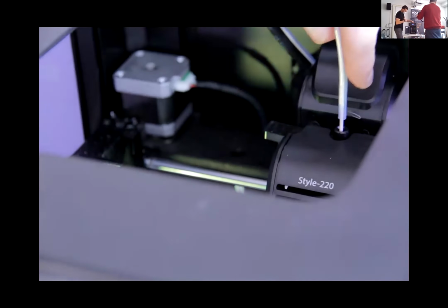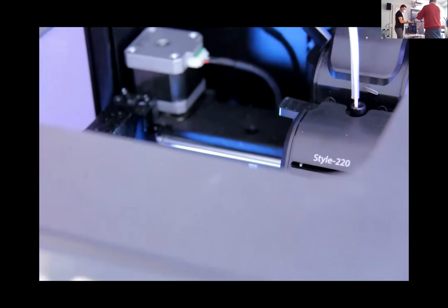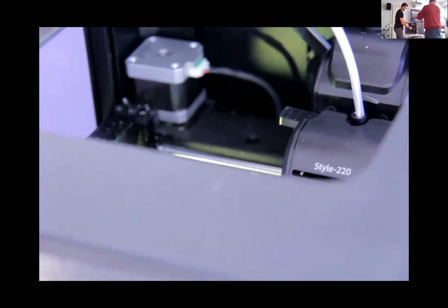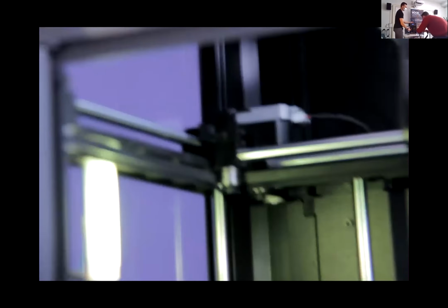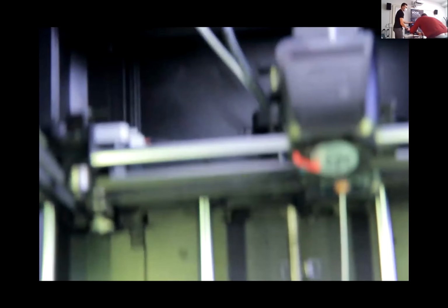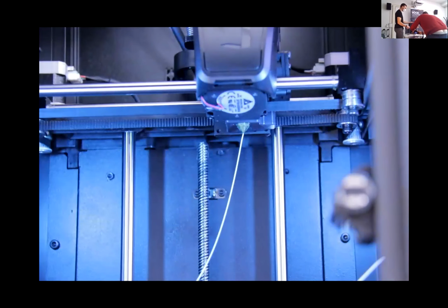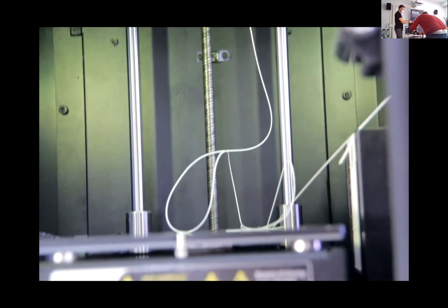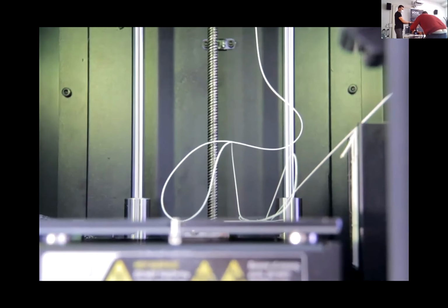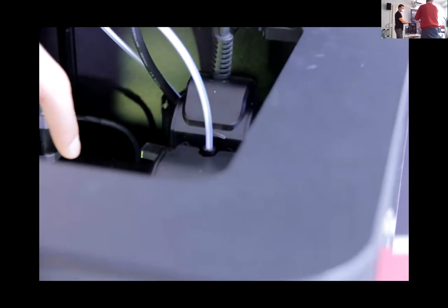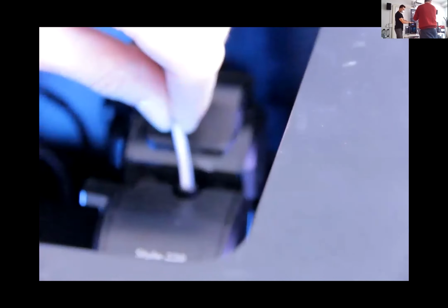There we go. So it's actually pulling on the filament now, pulling it through the printer. And if you look down at our nozzle, you can see the filament coming out that it's pulling in to the hot end, which is great. Let that go a bit. And we also want to make sure our Bowden tube is pressed into the top of the hot end properly. So that's this clear tube on the outside. And we're just going to push it in. So it feels like it's in pretty good.